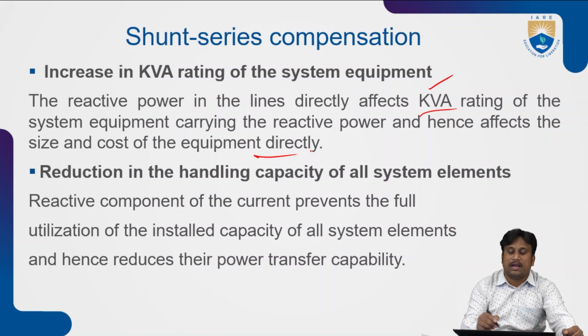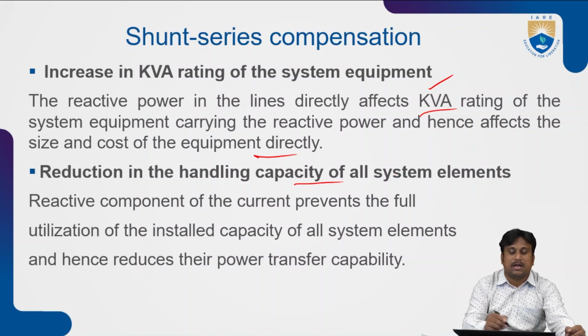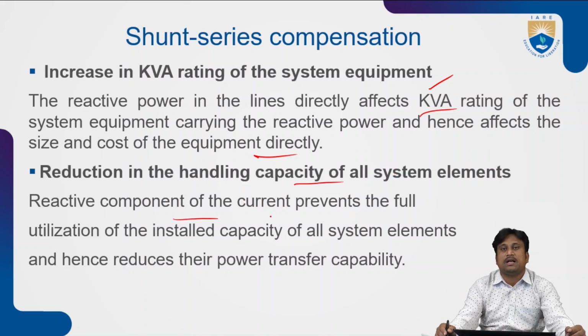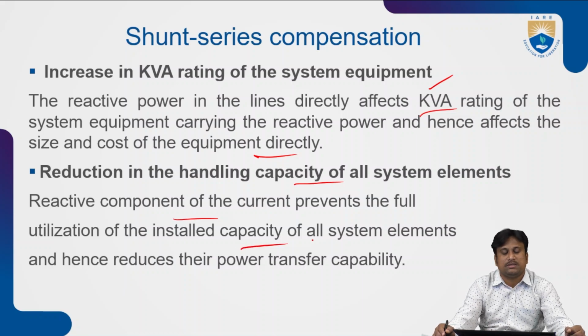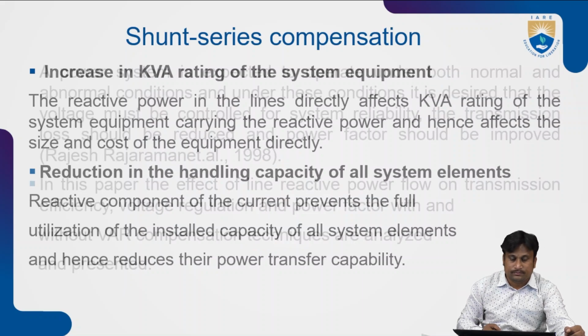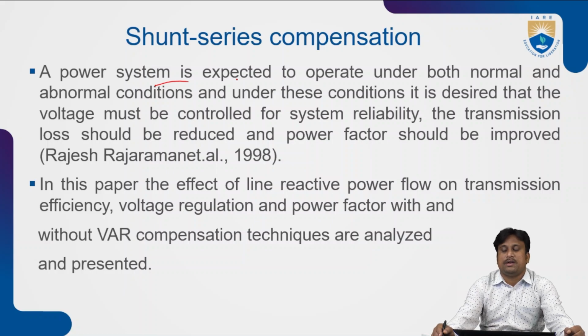So reduction in the handling capacity of all the system elements takes place. The reactive component of the current prevents the full utilization of the installed capacity of all the system elements, and hence reduces their power transfer capability.